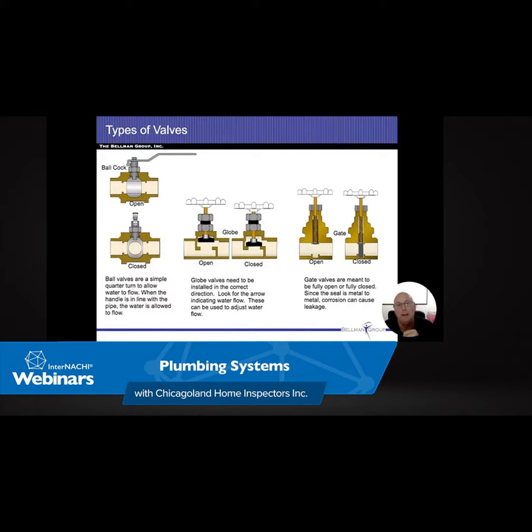I used to have this Toro, it was a Toro static and a Toro residual gauge together. And it was mostly designed for determining if you had enough water flow to install a water sprinkler system outside for your yard. But it did help determine what the static pressure was and also the residual pressures. But we don't really do so much of that here. We're more concerned of the term functional flow.